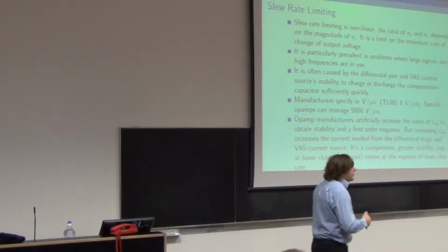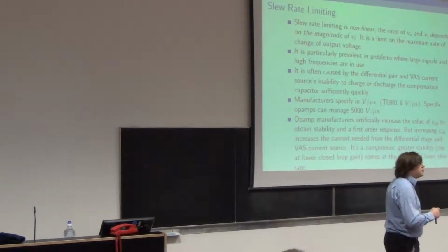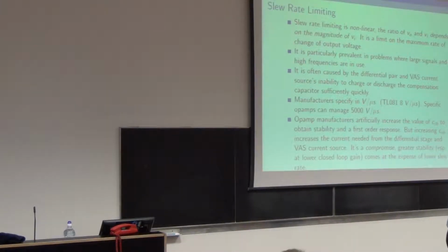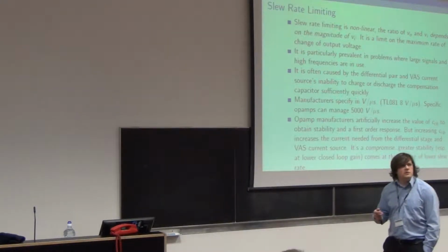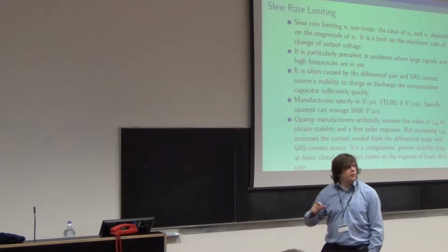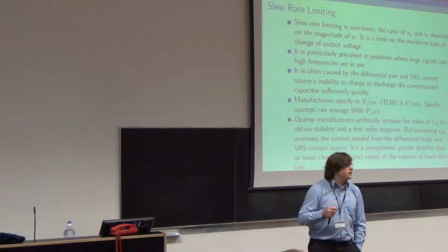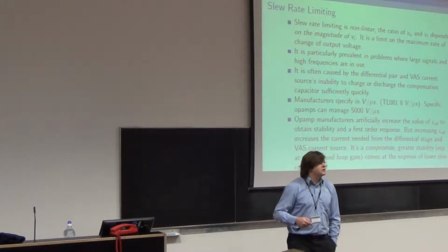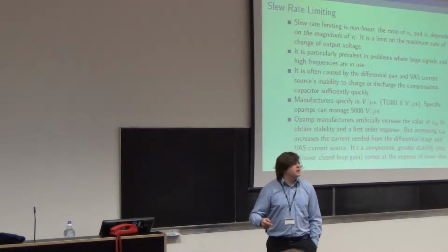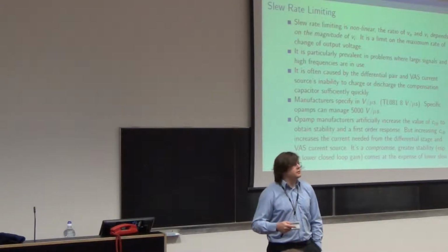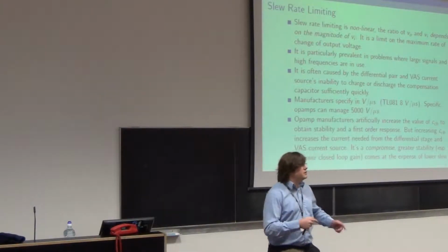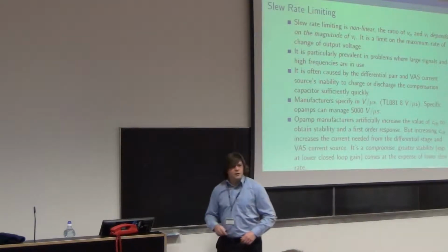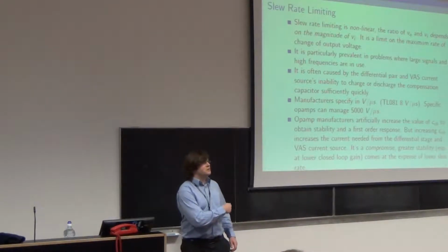If you put in a small V in, you get a small V out, maybe there is some limiting. If you put in a bigger V in, you will get a bigger V out, and the nature of that limiting will be different. That is to say, you may find the slope is the same, but the limiting will start at a certain point, which depends on the size of V in. That's what makes it non-linear. If we have the same response, irrespective of the size of the signal, really that counts as a linear system. Because all we're saying is it's first order, and a first order system is linear, secretly.